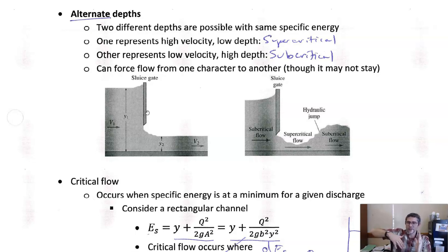You could put a little check dam in there, a little dam that has a weir, with flow over the top. That's one option, but then you're going to get silt accumulating behind the dam, and maybe that's okay, maybe it's not. A sluice gate has the advantage of backing up the water for that intake to go in, but keeping silt able to be moved down the channel. So you see sluice gates a lot in agricultural situations.